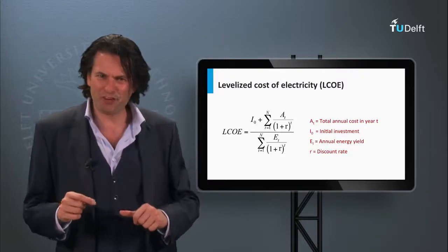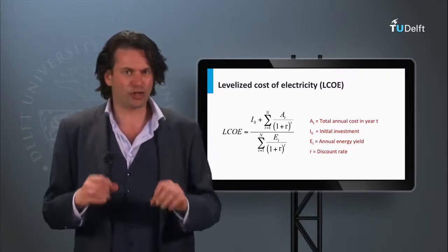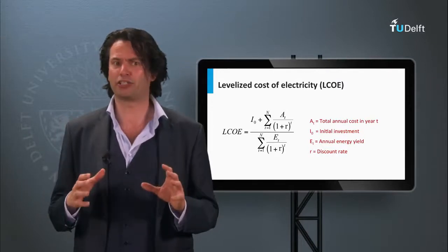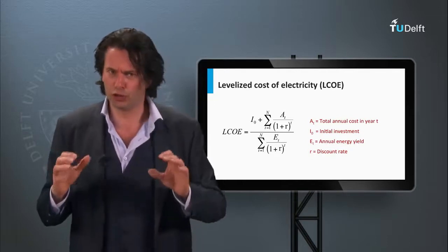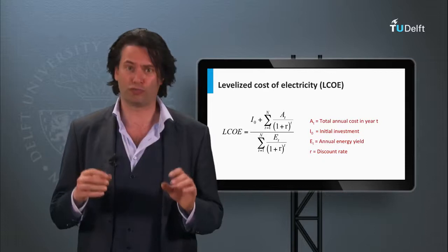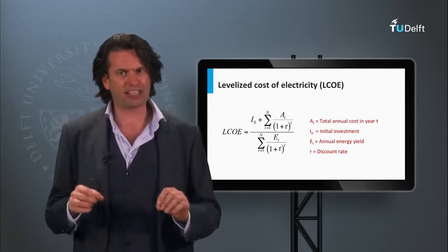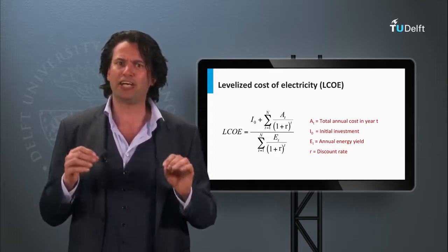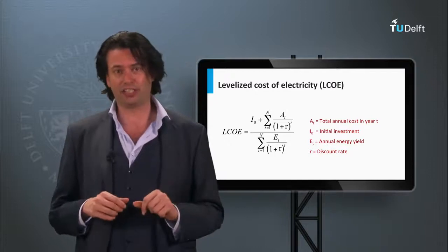Based on the size of the PV generation and the cost of materials, the levelized cost of electricity of the PV project could vary a lot. Also, the discount rates used for evaluation will have an impact on the levelized cost of electricity value. For the power producer, the levelized cost of electricity is a valuable indicator of the cost competitiveness of a certain energy technology.